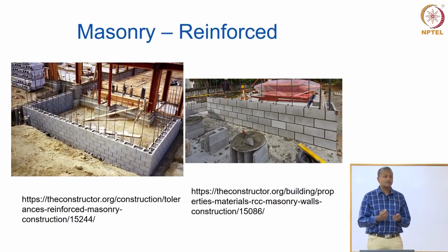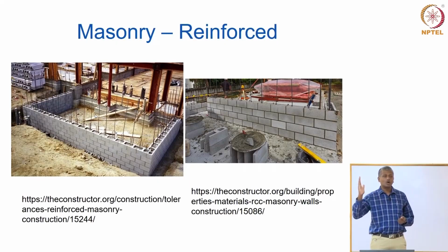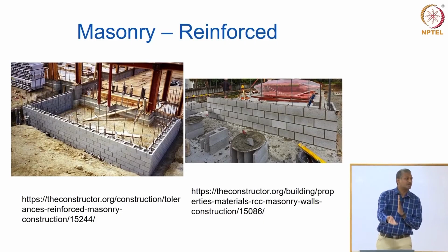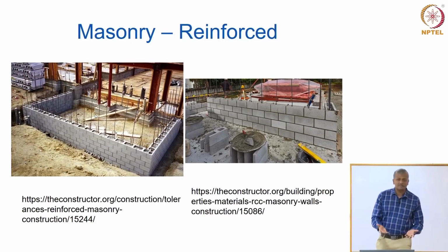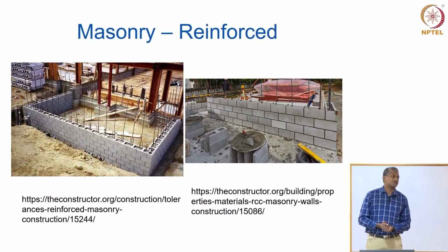So in earthquakes, you can imagine that the structure actually has a motion that is moving along with the ground, right? In such cases, just having a good strength in the axial direction is not going to help. So you need to start providing some degree of load carrying ability which can actually take the loads in the lateral direction. In such cases, providing a reinforcement can go a long way in actually extending the load carrying ability of your masonry.